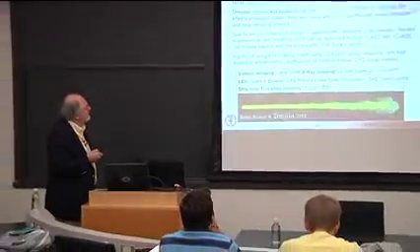Thanks, that's a good question. All right, I'm just going to show the last slide, and we can take some more questions for this section. So this approach that I've just shown you here is called the discrete droplet model approach, or the Lagrangian drop, Eulerian fluid approach. So we track the droplets using Lagrangian coordinates. The gas is solved using the Eulerian field equations. And basically, you'll see this in pretty much all two-phase flow codes, especially for engine applications. It's in Fluent and many other codes that are also used for two-phase flow modeling.